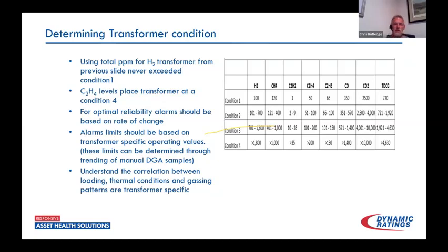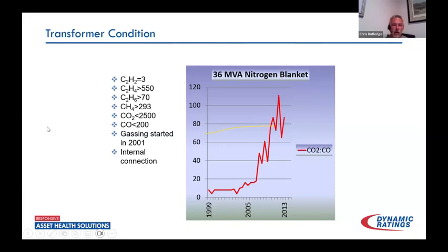And also, when we take a look at the CO2/CO or carbon dioxide ratio, we see that it had been fairly consistent, but is steadily climbing. Now, this is never going to be a perfectly linear graph, but we can see that we're up and down. And again, highly dependent on temperature. When was the sample taken will affect this greatly. How well was the sample taken, as carbon monoxide tends to escape the atmosphere rather quickly as well. But we can see overall, if we put a trend line on this, we do see a pretty steady increase in that ratio.